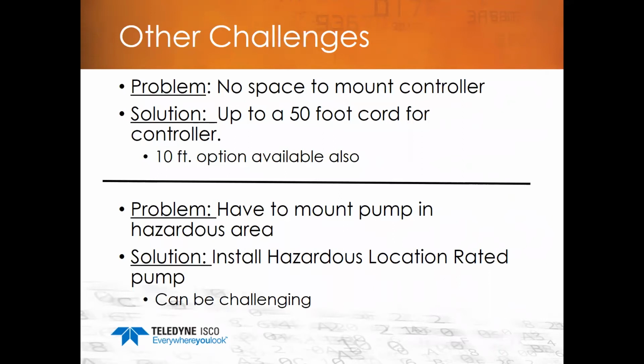It's a very explosive hazardous area. I think Class 1 Div 1, it happens that way. But if it's just a general hazardous area, not Class 1 Div 1, but maybe a Class 1 Div 2, we do have hazardous location pumps available that are set up for arcing and sparking for use in those areas. But it can be challenging. Fitting something in an area that has a hazardous location rating can be difficult at times. So consider that, look at that, and think of all those pieces.